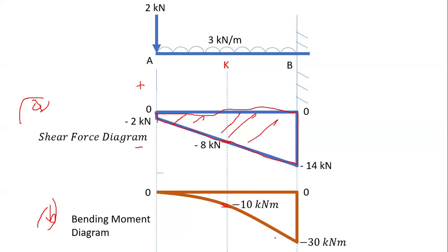So once you mark them out, you do the same from point O there. You join those points with a very good line. Unfortunately, this time, the line is no longer straight, it's parabolic, it's a curve. Just like as you saw for the shear force, the line was at an angle. With this one, the line goes like that as a curve. Again, if you want, you can feel free to shade.